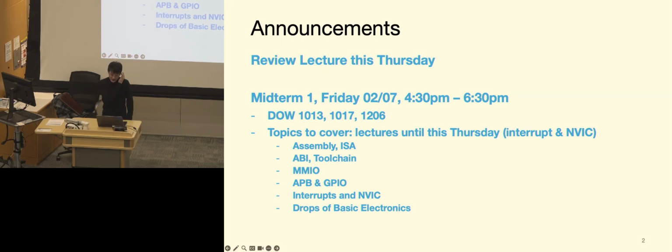And then MMIO, the memory mapped IO, and APB and GPIO pins, the GPIO channels that we talked about: input, output, different modes, and how you connect them to the P-select signal and the P address, if you want to determine the registers of one peripheral, as well as P enable and all these signals, and how they work.